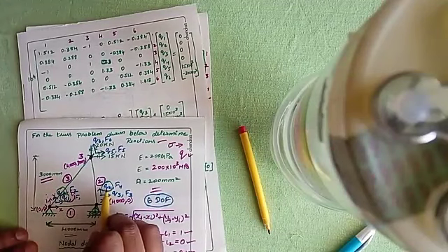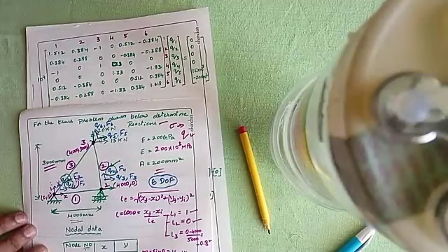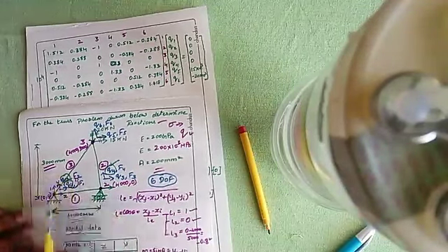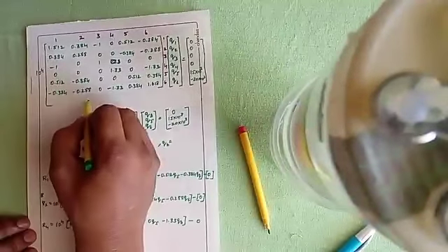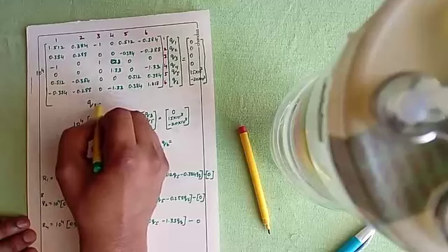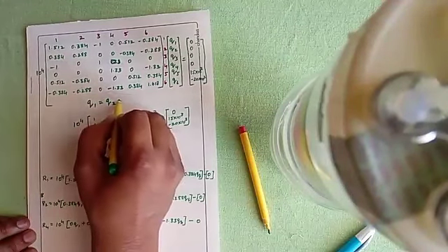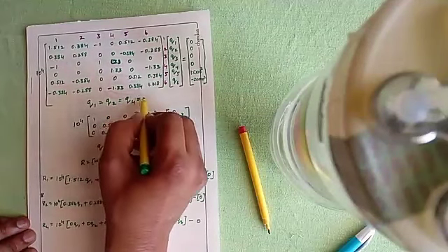Along the y direction, what is the displacement? Q4 is my displacement, which will be completely restrained. And similarly, Q1 and Q2 are completely restrained. So by the elimination technique, if I apply boundary conditions, I am assuming that Q1 equals Q2 equals Q4 equals 0.